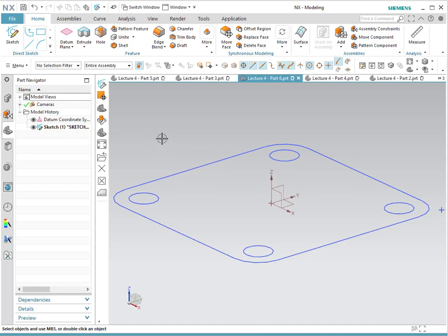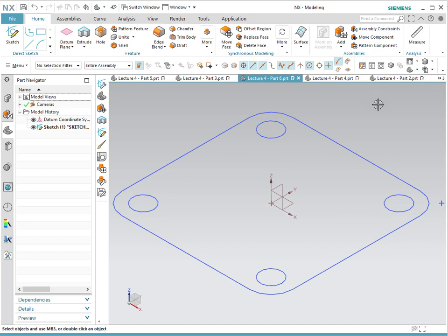Extrusion is a method which adds material perpendicular to the sketch. In this case, the material will be added either going up or going down because the sketch is created in the top plane. I advise you, whenever you do revolutions or extrusions, to have your sketch in a three-dimensional view or an isometric view so that it's easier to see how the process is done. To do so, simply go to this menu over here. Notice that it gives you different choices. You could use either trimetric or isometric so that you could see how it works three-dimensionally.